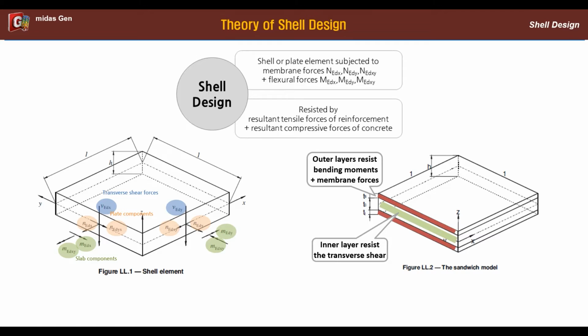The outer 2 layers are responsible for resisting bending moments and axial forces. The inner layer also resists shear forces as shown on the right figure. In addition, to mathematically optimize the amount of rebar, the theory of Thomas and Marty was introduced, and an optimal design function was added in the program.